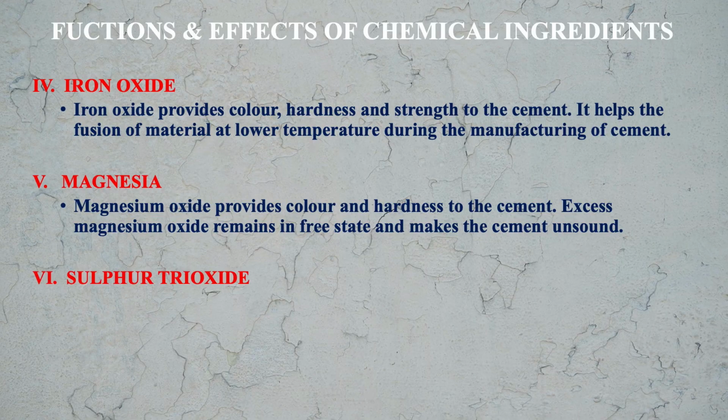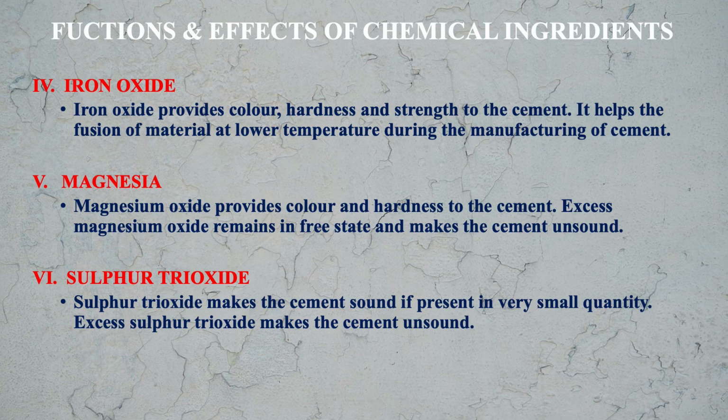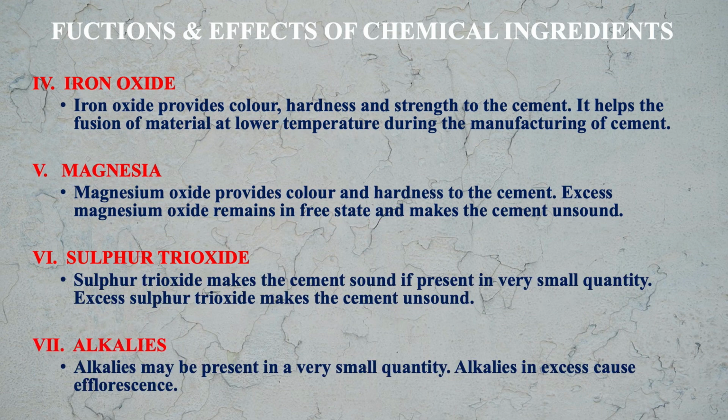Then sulfur trioxide. Sulfur trioxide makes the cement sound if present in very small quantity, but if it is in excess, sulfur trioxide makes the cement unsound. Then what is the role of alkalis? Alkalis may be present in a very small quantity. Alkalis in excess cause efflorescence, means it is also harmful.